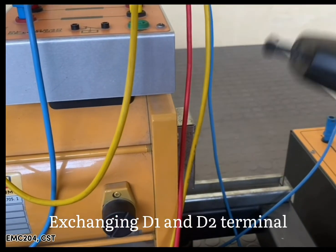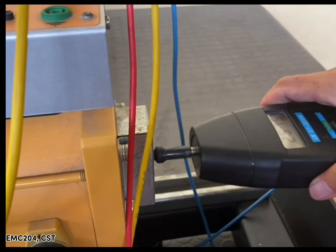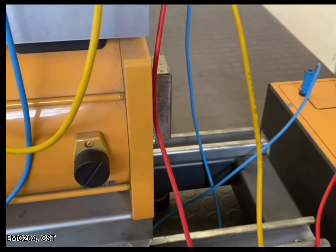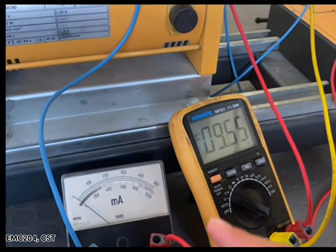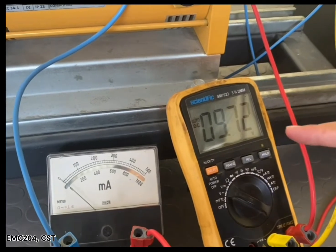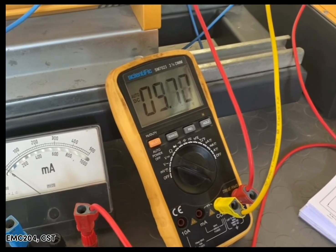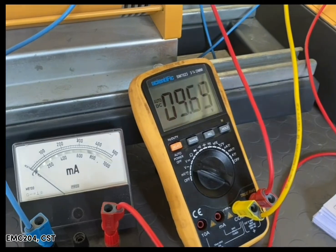Measure the speed of the generator. Here the speed given is 2576. It is constant, right? Whereas we also take the speed of 2500 on the motor side. Here at 0 ampere we got the voltage of 9.90. It is the residual voltage.